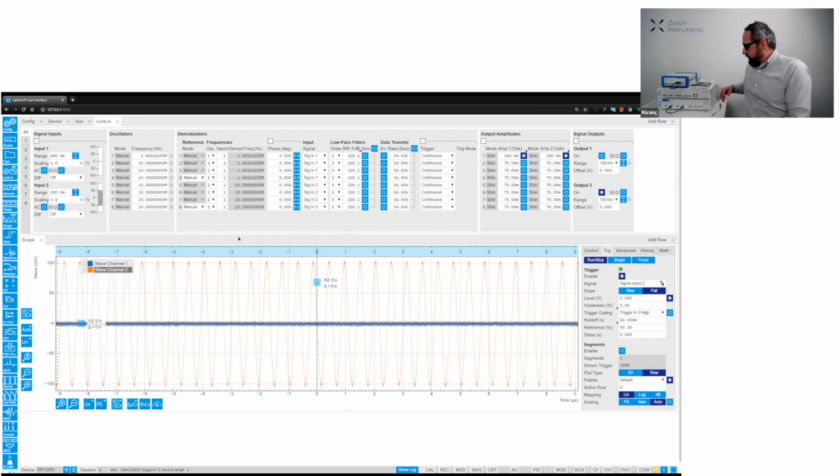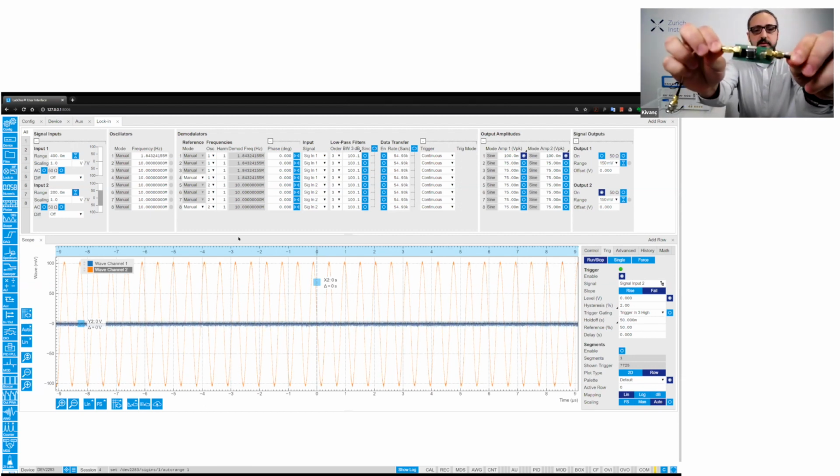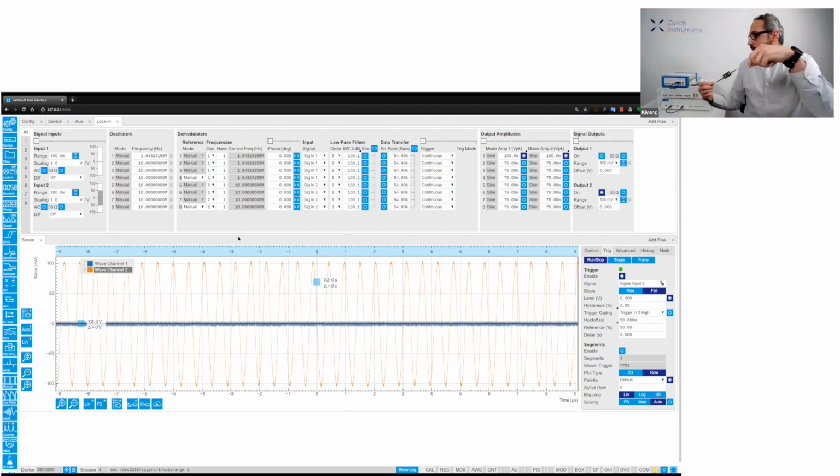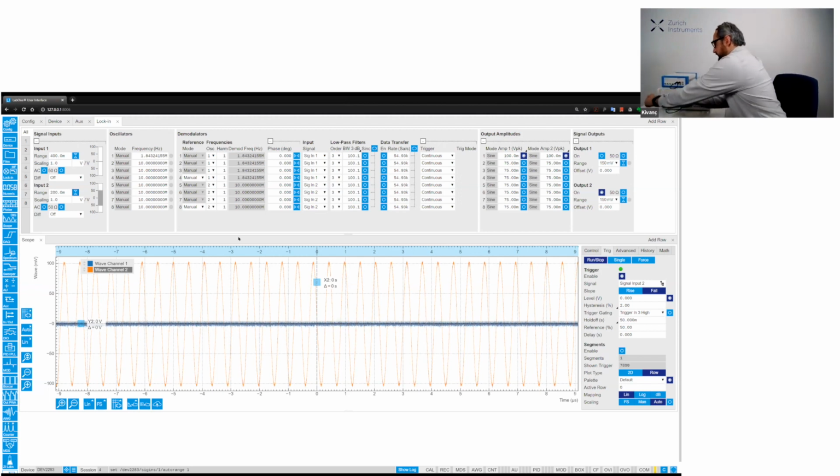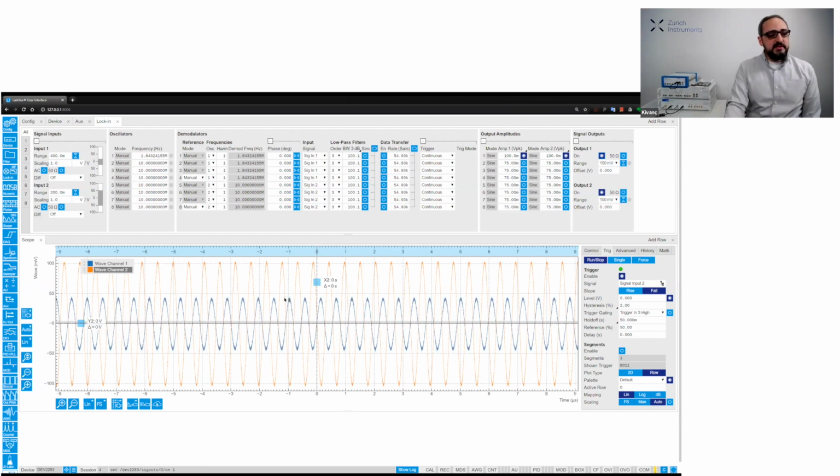I can also now introduce my device. So today I will be using this quartz oscillator as my sensor. I have 2 here, I will only use 1. And then I will also connect it between these remaining channels. And I start driving it, and already see the signal on the scope as well. It is much less amplitude, and also we have a phase delay that comes from the DUT.